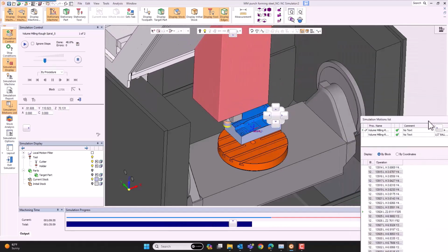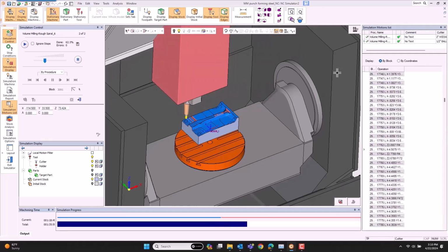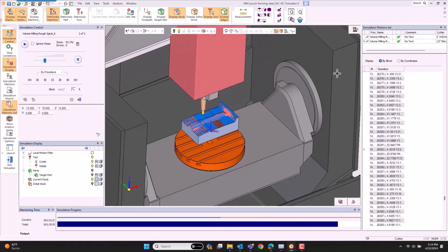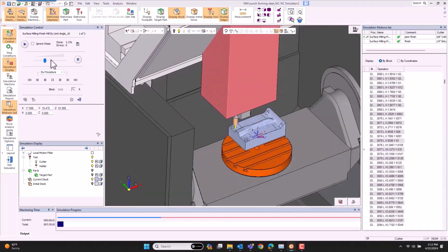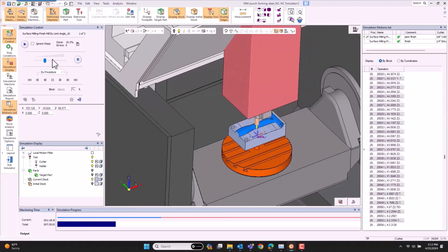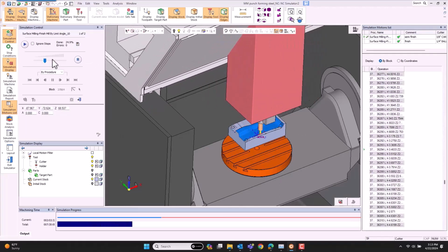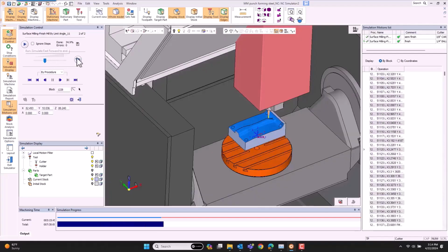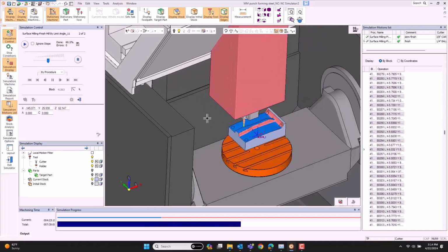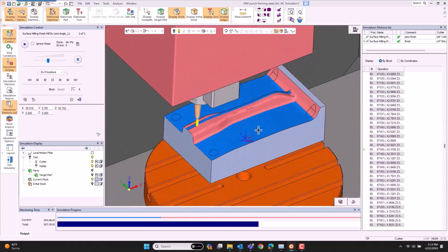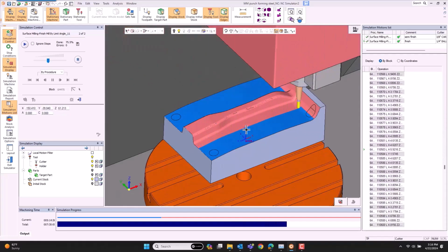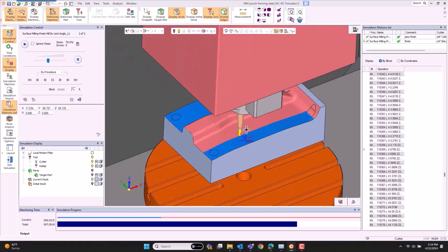Here you're seeing a full machine simulation. It could be just the individual part, like you see a lot of different simulations plot. Let's pull the G code up, and as I go through the rough cut and now through the semi-finish, you can see how it's targeting just those stair steps, just that remaining material condition. Here you see it taking a Z level and then a lace cut for a finish. So all that is controlled so that I get the quality of cut I want. It could be a remachine too, where I go back and pick out those corners.